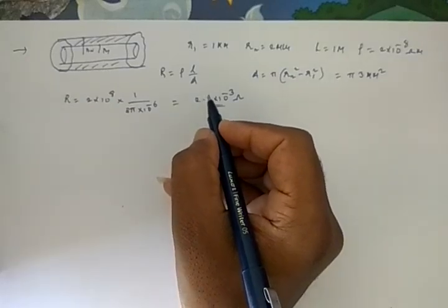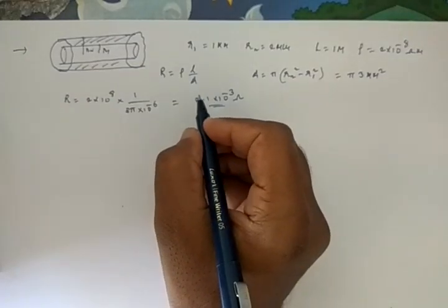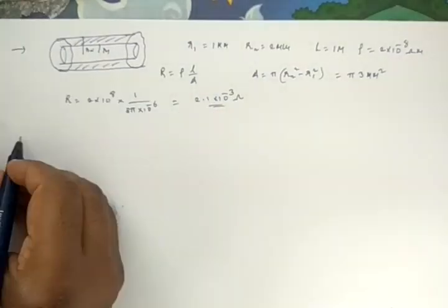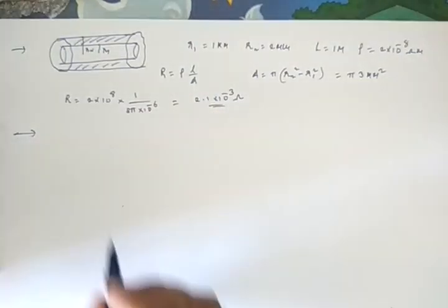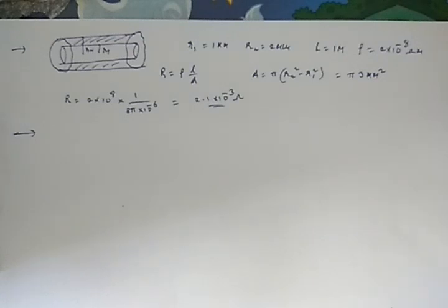So now look at the next question. The resistivity of a platinum wire at the ice point is 5 ohm and at the steam point is 5.39 ohm. When the resistance of the same wire is measured in the laboratory, it is 5.12 ohm. Find the temperature inside the lab.